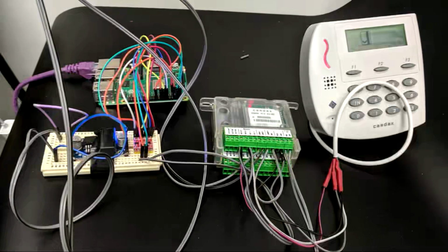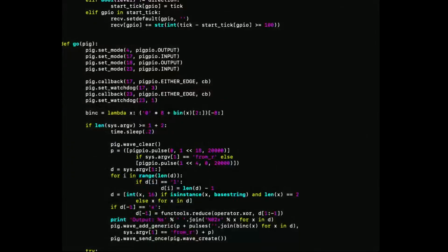So what we can do is build a tool to man in the middle the protocol between a reader and a controller, just to verify, and this is how you find this out anyway. So from left to right, we've got a power supply thingamajiggy, a Raspberry Pi, a G-Bus I/O unit, which is basically just there because reasons, and then a reader. All you need to know is that the Raspberry Pi is intercepting the comms between the reader and the controller, which is one of the cables going up. Can't see the controller. It's just good old-fashioned Python on there using PyGPIO, and that's pretty simple.